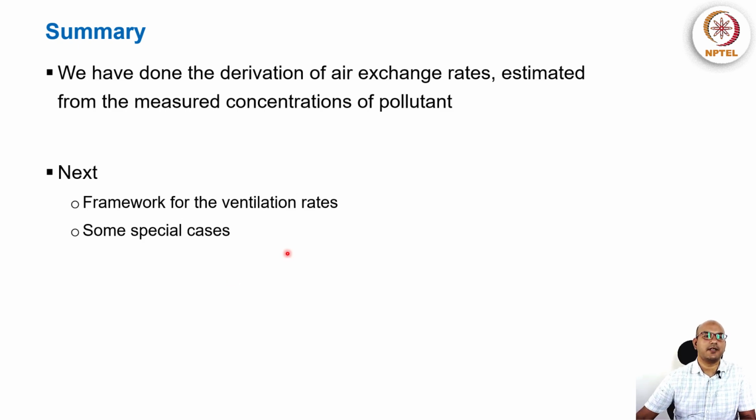So in summary, in this lecture, we have done the derivation of air exchange rates or air exchange rate constants estimated from a measured concentration of pollutant either in a build-up phase or in a decay phase. Now in the next lecture, we will look at the framework for ventilation rates and also some special cases.